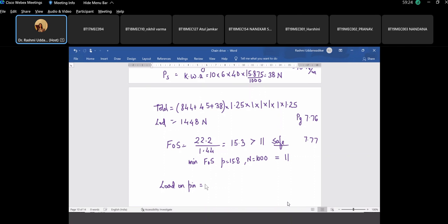Yeah, it is because it is metallic. Since it is metallic, the weight of the chain is high. Since the weight of the chain is high, if it fails, it will be thrown away. The links would be thrown away at a very high speed, and this cannot be accepted. And so the standard manuals say that this factor of safety has to be very high.